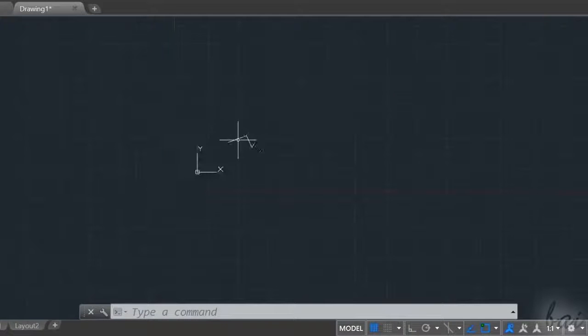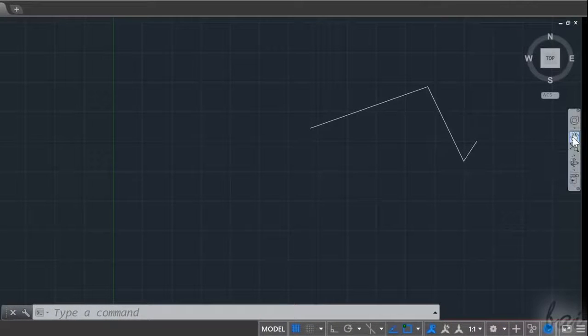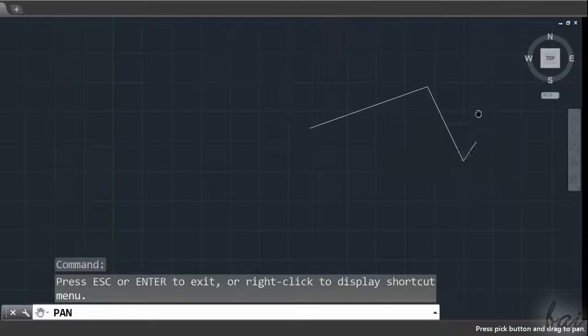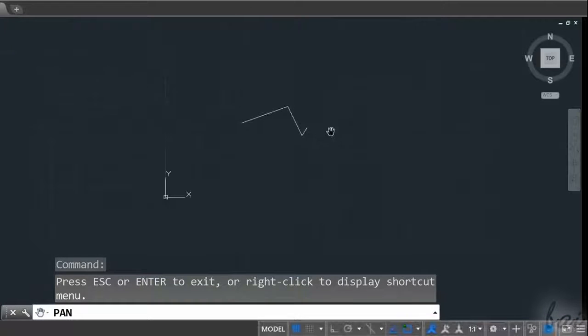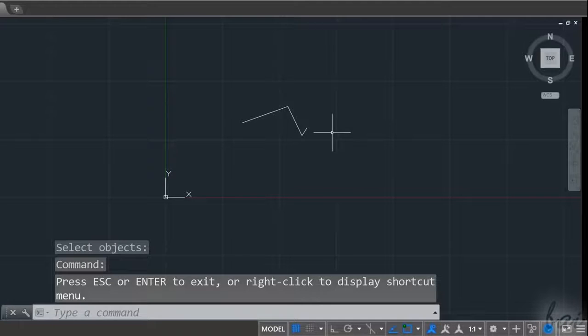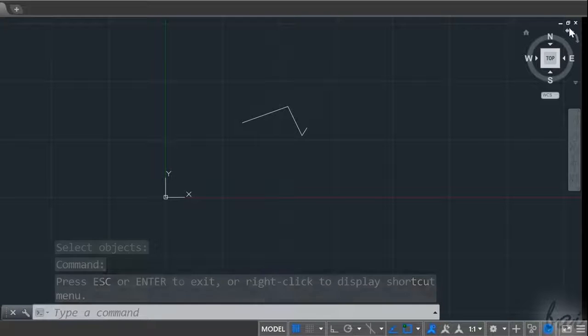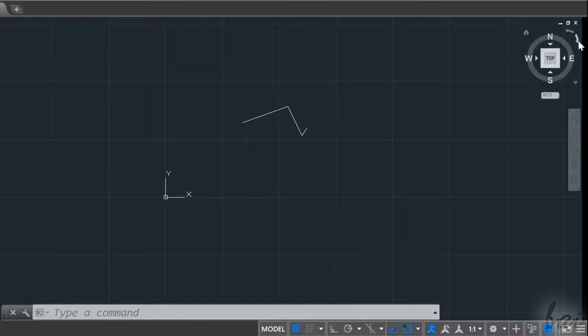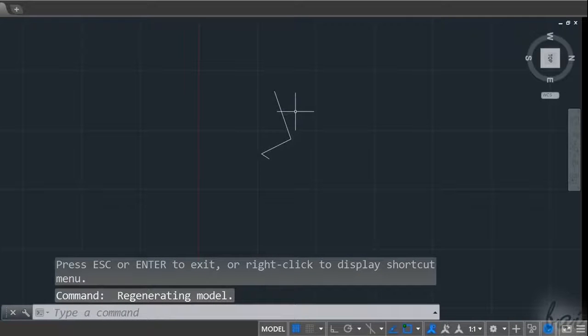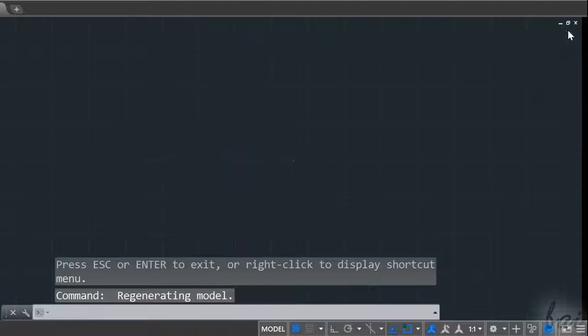Let's see all you need to know to check and preview your project in progress. Use your mouse wheel to zoom in and out. To move around, enable the Pan tool on the extreme right and click and drag. Finish with Escape. To rotate your point of view, you can go on the extreme right on the Rotate buttons in the top right corner of the 3D View cube.